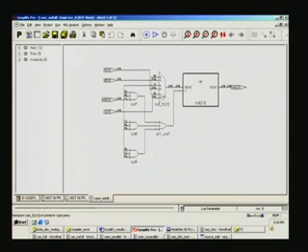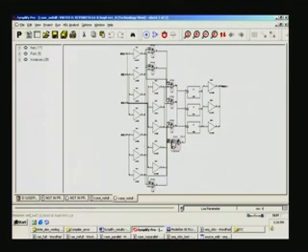So that is quite a substantial saving, and if you view it once again, it is the same 2 plus 2 4, then 6 here, one extra LUT has come over here, and the count of input buffers and output buffers essentially remains the same, and only this has made a difference, and plus you see the latches here.